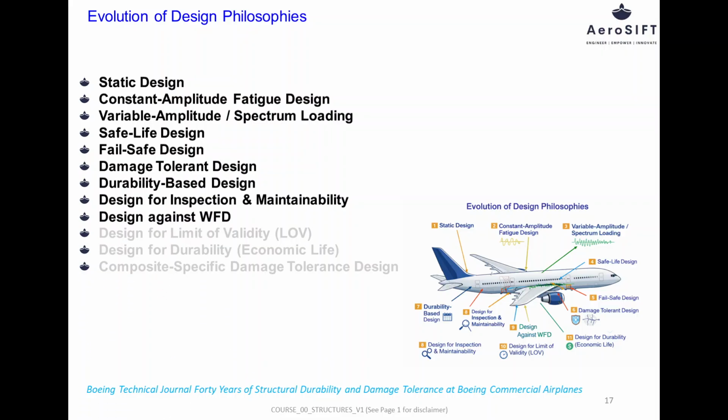Design against widespread fatigue damage addresses the risk of multiple cracks developing independently at adjacent locations and eventually joining together. Such damage can reduce structural strength more rapidly than predicted by traditional damage tolerance analysis. This philosophy requires special evaluation methods, inspection start points, and mandatory modifications to ensure that widespread fatigue damage does not occur during the aircraft's approved service life.